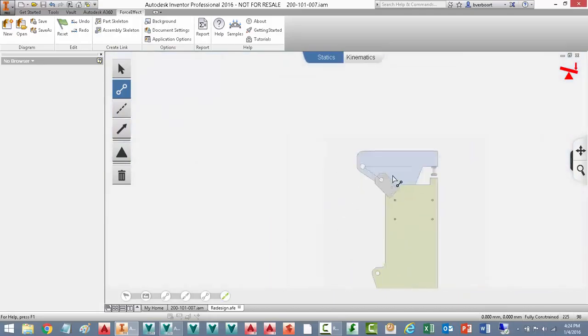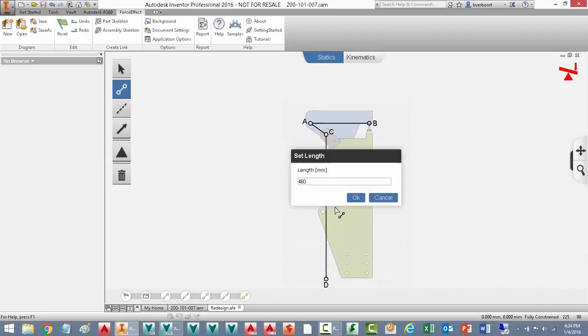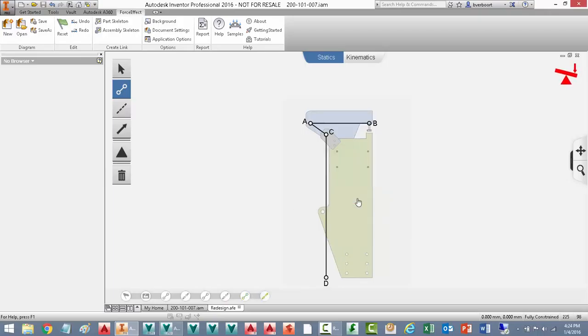Now we'll zoom back a bit, get a little bit longer range look at this assembly, and one more element that describes the back plane. We'll go with 455 on the length on that one. And then let's go ahead and add in a constraint to fix this. In addition, we'll add a constraint that will lock in this pivot point in position, making it welded.